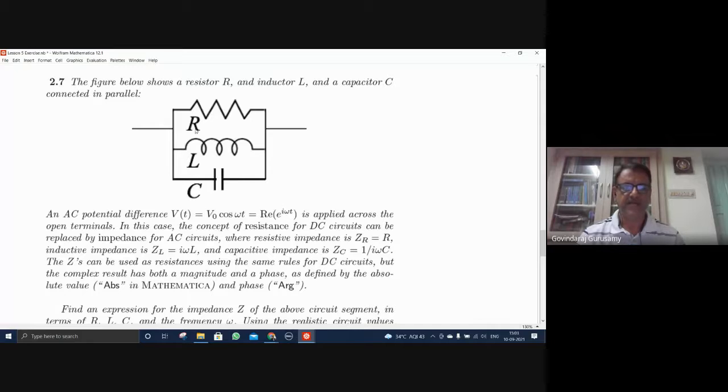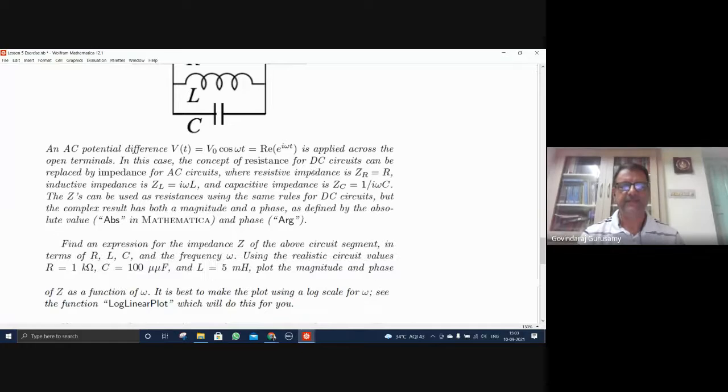It is going to charge a capacitor or discharge a capacitor. Here it is not simply charging or discharging, because an AC is given, so it will get charged and discharged. How fast or how slow you are going to charge it will be decided by the R and C, and that is the time constant. The time constant is responsible for the fast or slow rate at which the capacitor is charging or discharging.